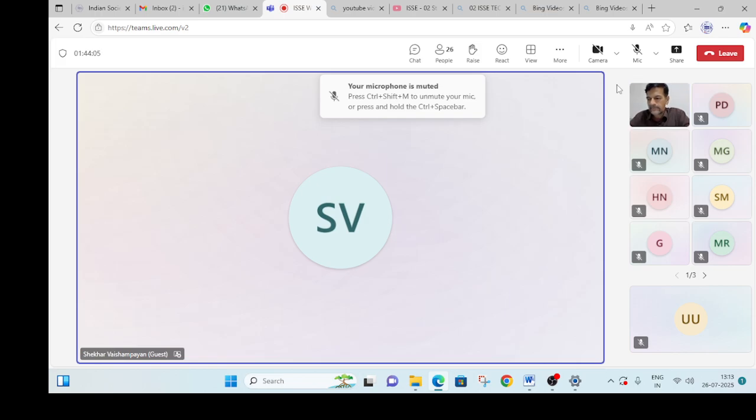But today what tends to happen is people don't go for this kind of huge height of concrete now. People are now saying that they will do concrete in layers of 1 foot, 300 mm only. If you use concrete in 300 mm layers and you roll it down, instead of compacting it, you move a road roller, a fabric roller, on top. So the heat of hydration is very limited. That's called roller compacted concrete.